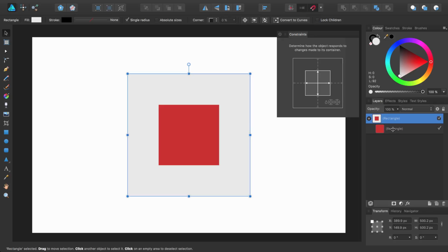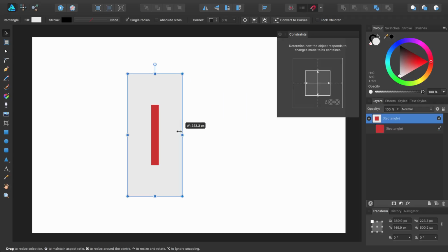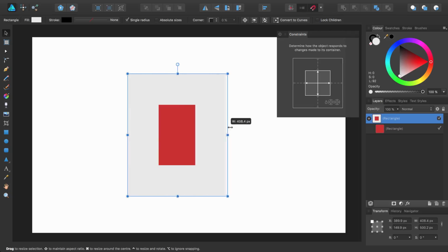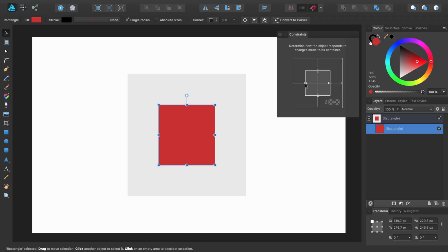It's worth noting that if you anchor content on opposite sides, as I have here, the red square is forced to resize to honour the anchoring on both sides, even if scaling was disabled. This situation is indicated in the panel by a dashed white scaling arrow.